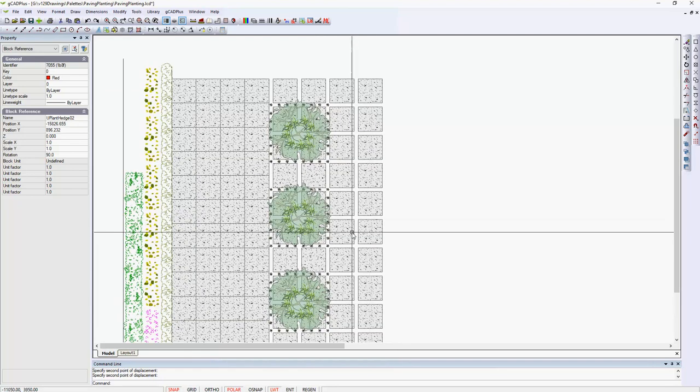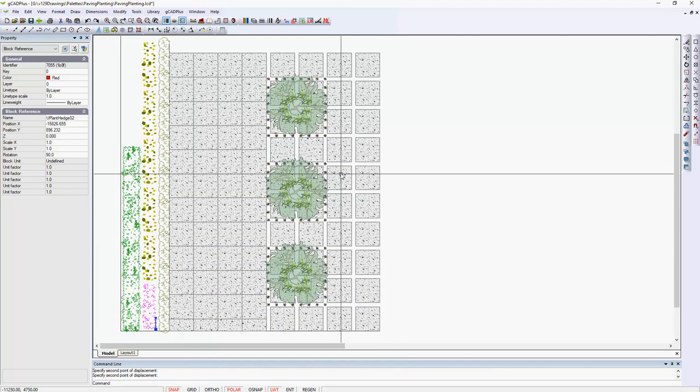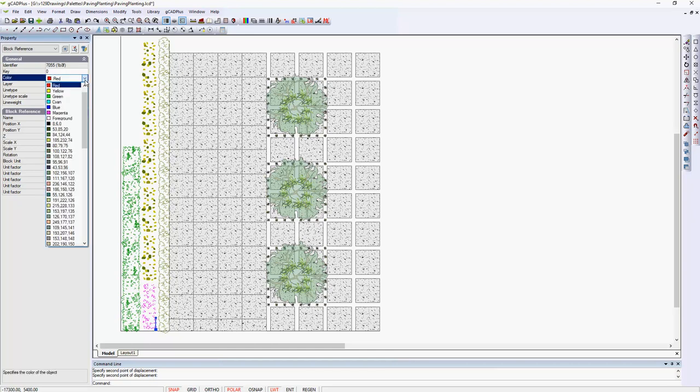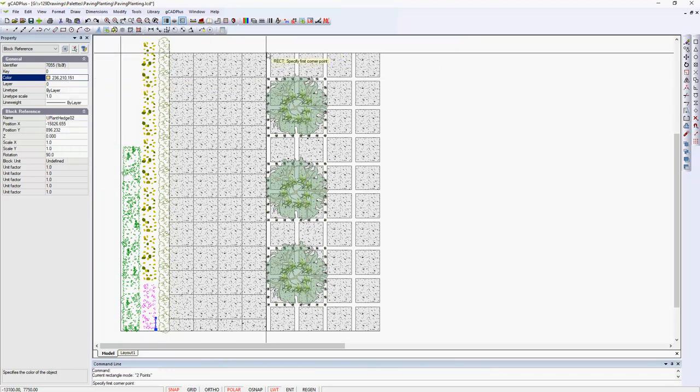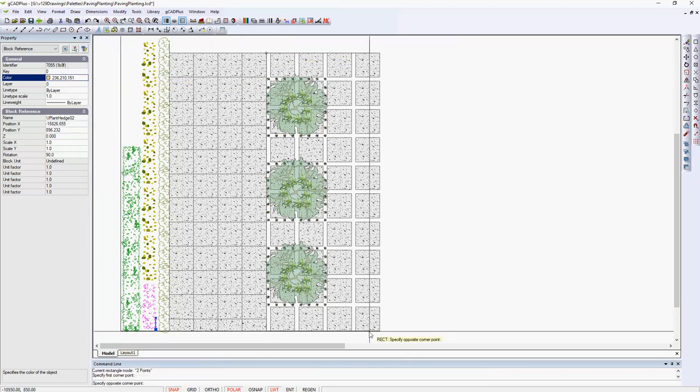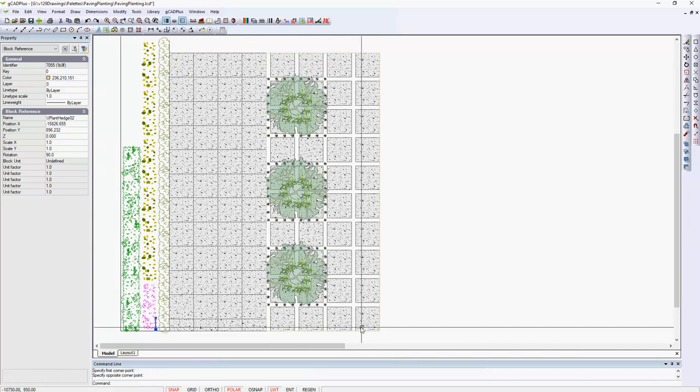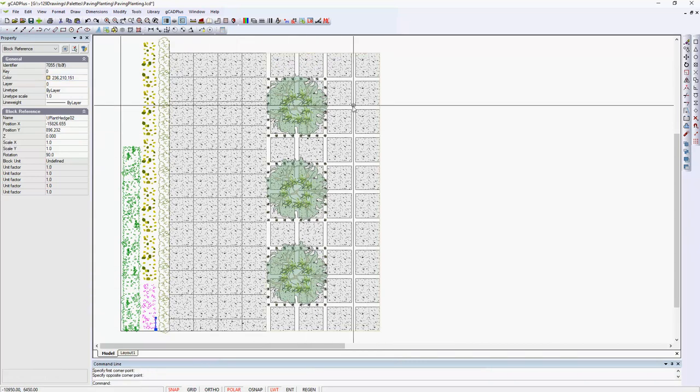But in this zone on the right hand side, I'm sure I'll change my view. I'm going to change drawing colour to a sort of crushed dolomite background colour for road base or whatever we choose to use there, and draw a rectangle, and for the moment we'll just pick that point there and here and select that rectangle that we just put in.